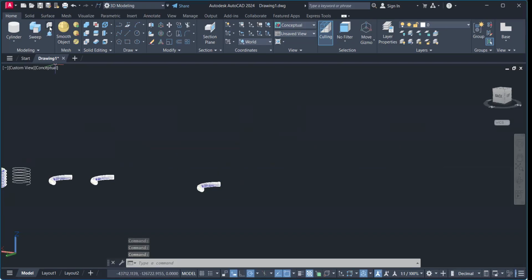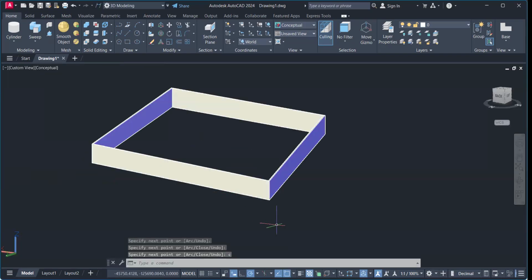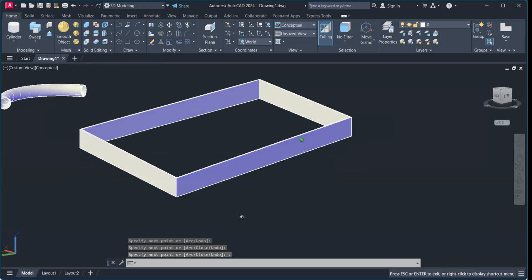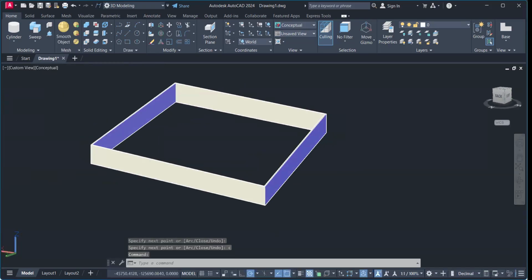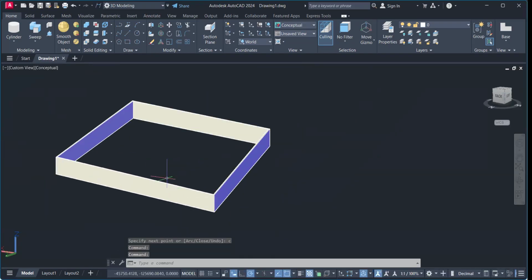And the next one we will talk about, the last option, is polysolid. What is polysolid? Okay. As today's last topic is polysolid. Just click on polysolid first. And polysolid is what we use for making a solid object, and then see enter to close, and then what goes here for creating. For civil architecture, it is mainly used for making the outer wall directly, by use of solid work.